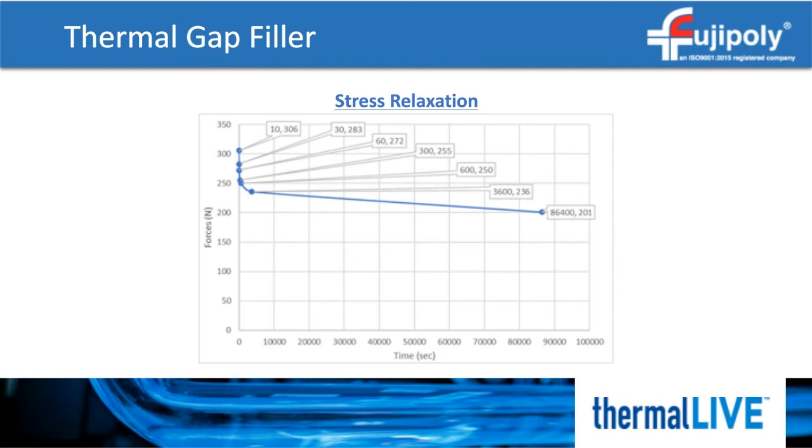From the graph you can see typically that at about 1 minute the stress has dropped about 12%, and this is going to vary from one material to the other. The force will continue to drop after 1 minute and typically begins to stabilize at 24 hours. Now, we don't require or suggest waiting 24 hours, but applying a fixed load and waiting 1 minute or two will help as opposed to compressing at a fixed rate, and certainly better than an uncontrolled compression.